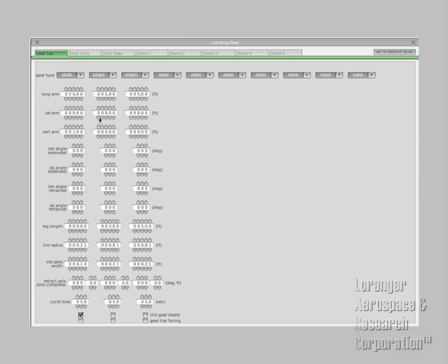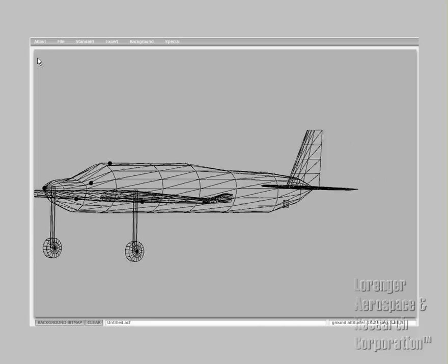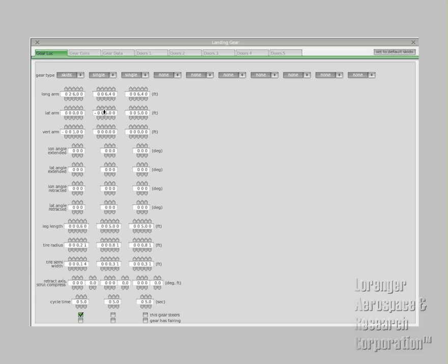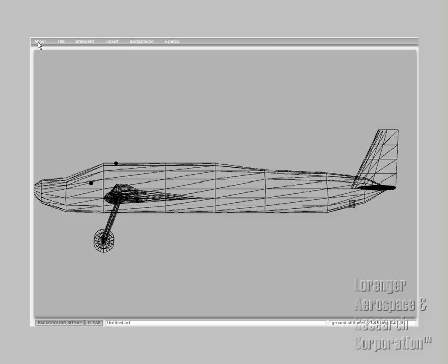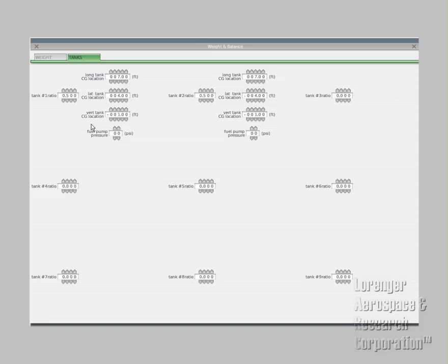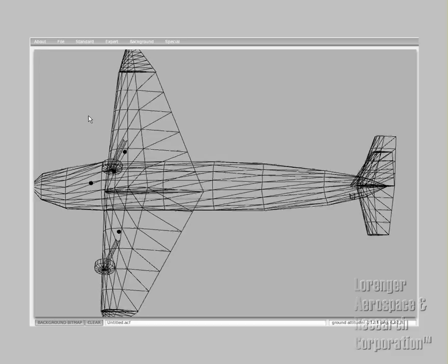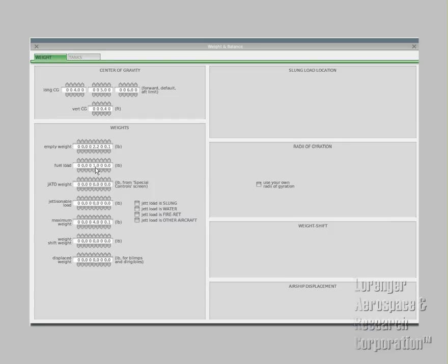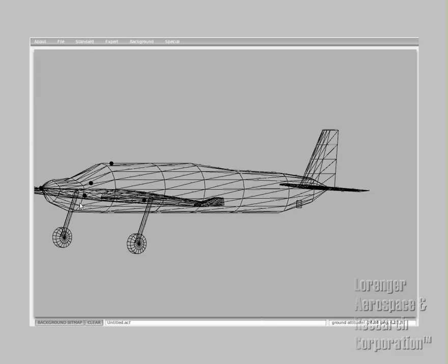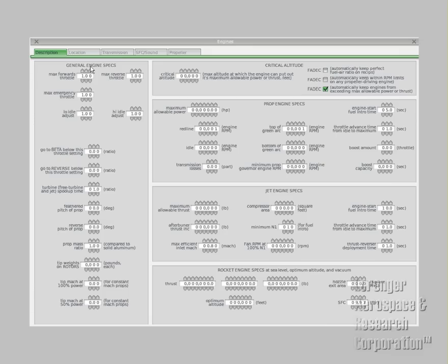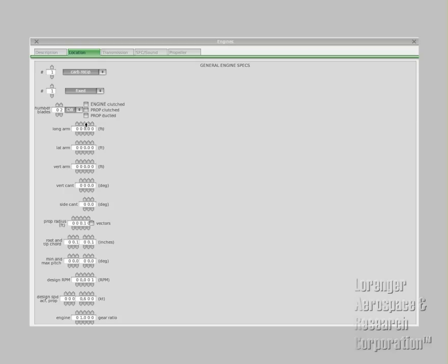Here you're going to add your landing gear. Real simple. Notice there are symmetrical problems, minus and plus. Minus and plus. Left-hand, right-hand rule, coordinate system. Here it's self-explanatory. Longitudinal, L-O-N, means fore-aft, and lateral is obviously right-left. And also add your gross weights, maximum weights, payload, and what have you.